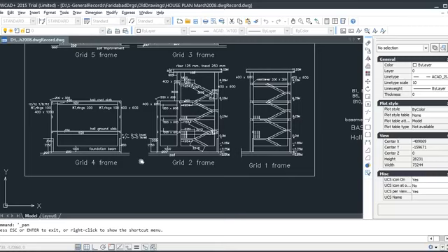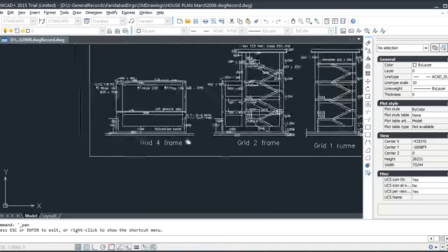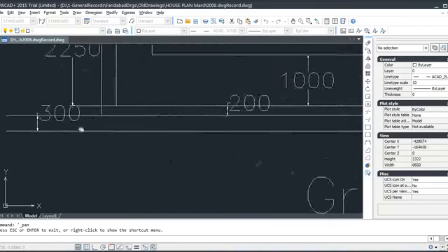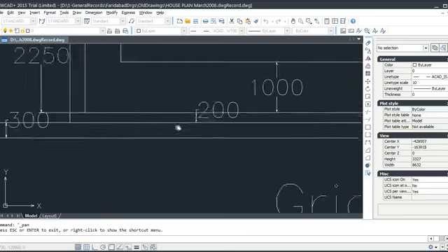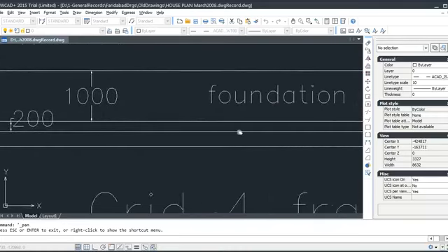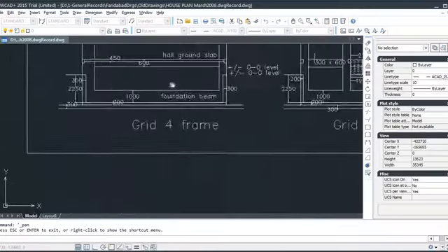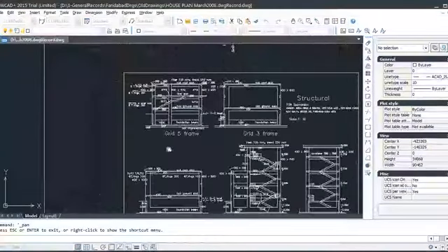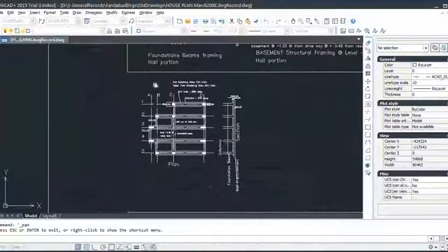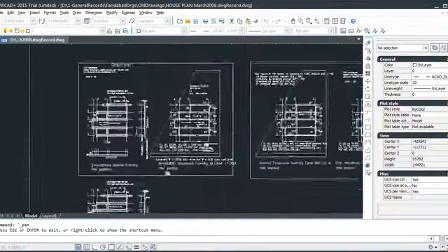So I removed 300, this 300 here, 300 1 feet approximately. This portion of clay was removed, otherwise I will start foundation here itself. No, I said no, I don't trust this clay. I removed clay throughout this. I mean to say throughout here. Complete plan, if you see plan of this, complete plan, I removed that one.